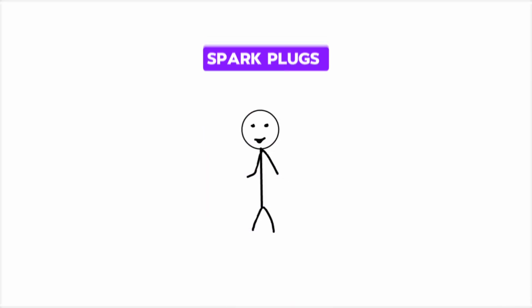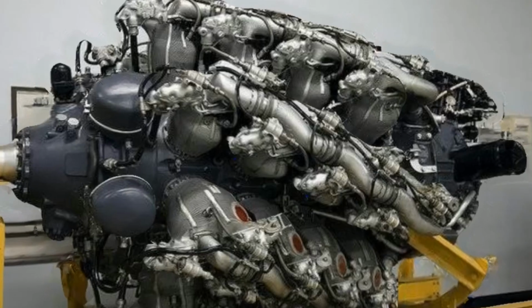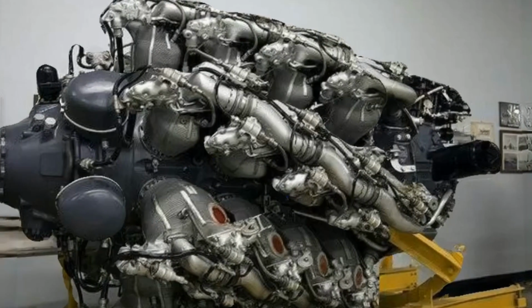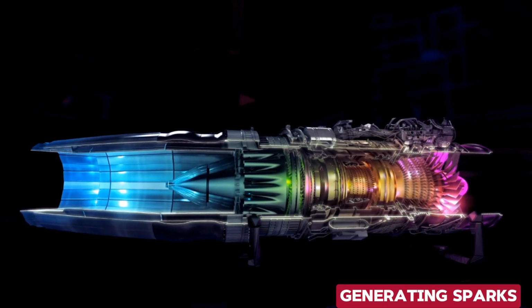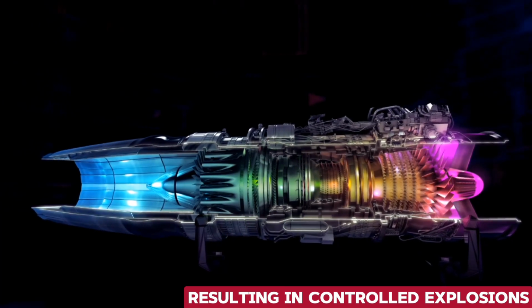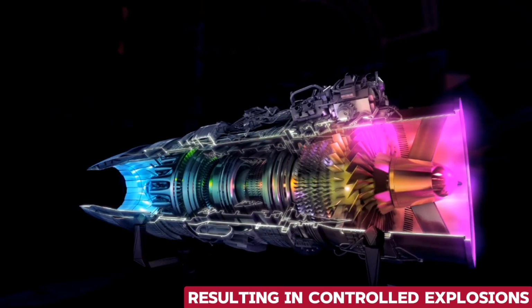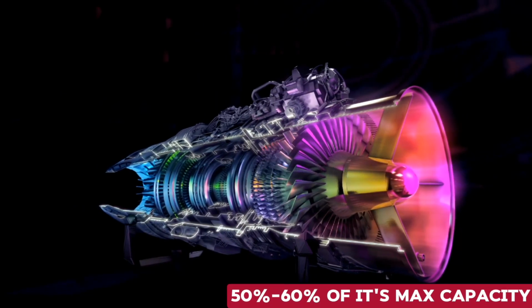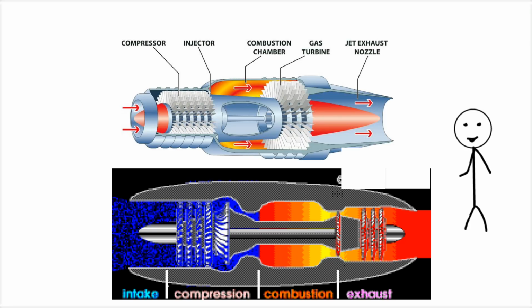The fuel is ignited using spark plugs similar to those found in household gas stoves. These spark plugs are important in initiating the combustion process within the engine by generating sparks that ignite the fuel-air mixture, resulting in controlled explosions. The energy released from these controlled explosions further accelerates the engine speed, typically reaching between 50% to 60% of its maximum capacity. At this stage, the air pressure generated by the compressor becomes so intense that it ignites the fuel independently of the spark plugs, indicating that the engine has become self-sustaining.